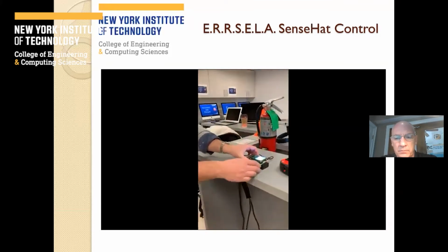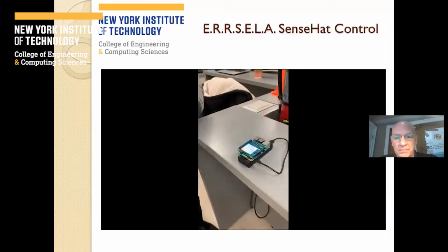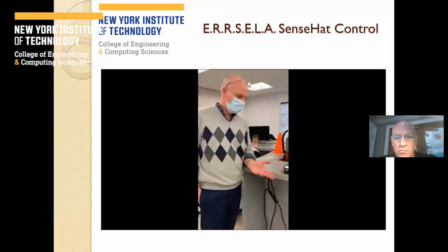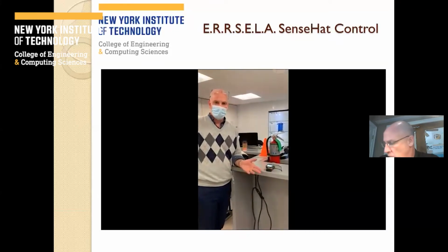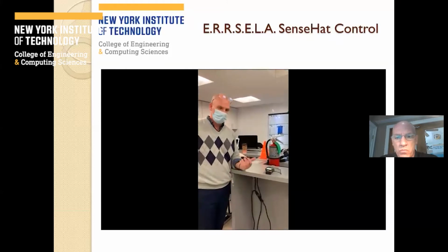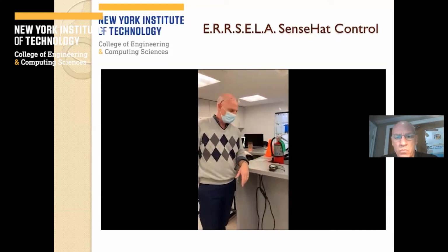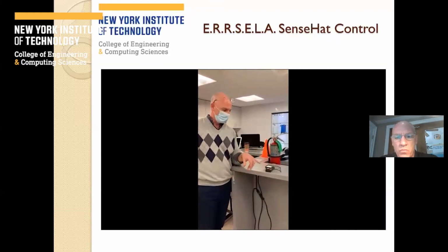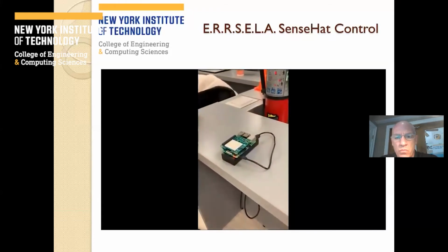And you'll see the device actually fire up. And the program, the code that we wrote, is going to initiate the accelerometer, and it's going to report forward, reverse, left, and right to make sure that the program's up and running. It was put into the ETC folder to make sure that it starts up automatically on startup. Once we see that, we'll know it's ready to go. So the program's actually loaded, and it's reporting forward, stop, left, and right is ready to be received.